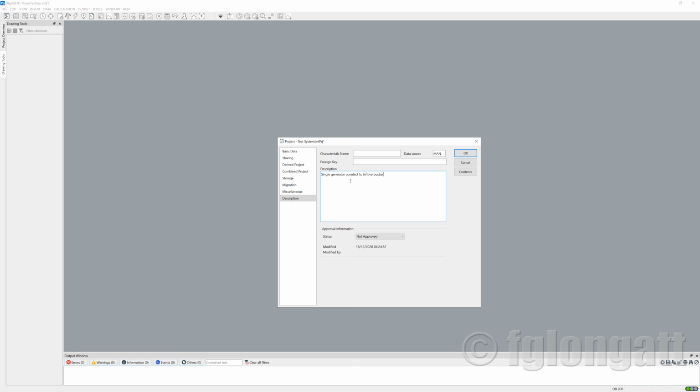My idea is we will start with this very basic system, and from there you will see that we will use it later for a very simple example about equal area criteria, okay? What I'm saying is that we already solved this test system using the classical equal area criterion, and we can get the results about the transient stability analysis.